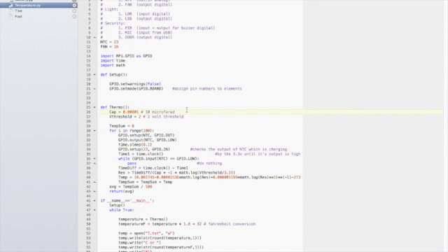But the one that we had did not work, so we had to do something about it. We got a capacitor that is 10 microfarads, and it has a 2 volt threshold. The idea was to charge the capacitor and discharge it and find out when the pin is going to detect it's on and when it's going to detect it's off. Using the time between those two, we can map it to the resistance of the NTC and figure out how much the temperature is.